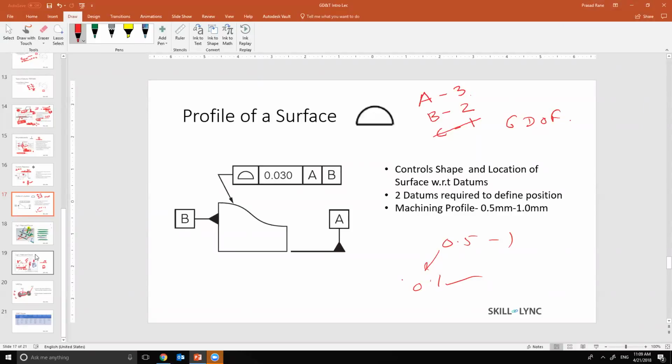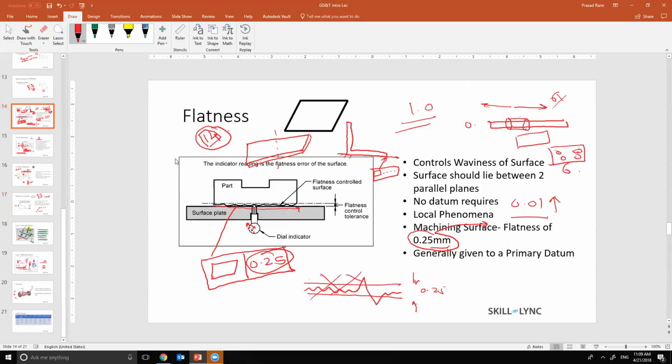All right. Thank you. Coming back to Lokesh's question, I think that was the slide on flatness, where you had a number like 0.25. Yes, this is the slide. Okay. So when I put 0.25, that is the worst case. This 0.25 is not obtained by any statistical method, it is not an RMS, and it is not an RSS or root sum square value. It's a worst case value. It means that on a very bad day, the point can lie anywhere between this point and this point.